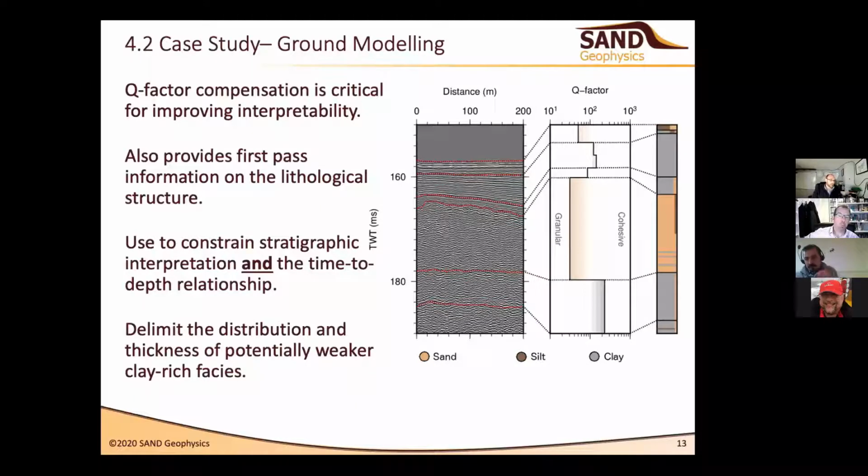I'll quickly go through the next couple of slides and get to the results, because I appreciate I'm running a little bit on time. Even though it was hull-mounted pinger data, we derived a range of different physical properties from the data. Probably the most useful at this particular site was Q factor, which enabled us to link the seismostratigraphy with the lithostratigraphy, because Q factor has such a strong response between drained and undrained soil behavior.